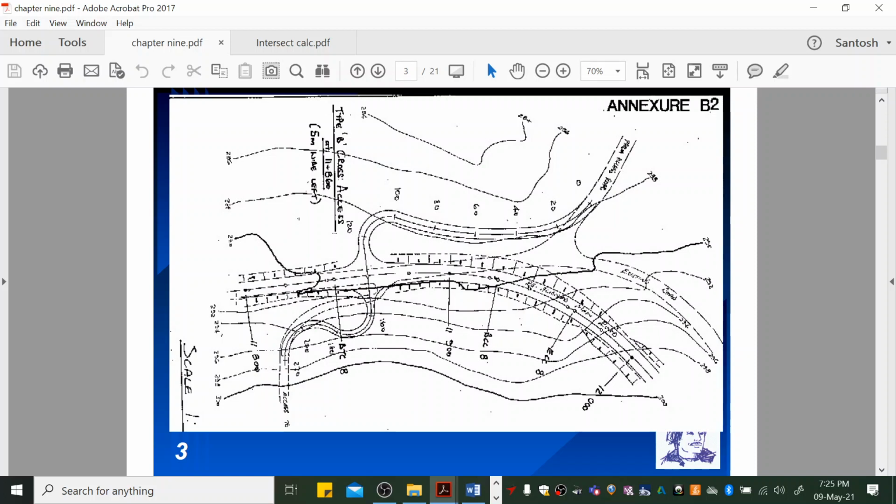So if one looks at it, we've got a main road that runs all the way through here. Then we've got two intersecting roads coming in on each side of the main road. And what basically happens is that the designers extract the ground profile of this road here. And they draw it, and you at Transport 2A will have to design an intersection, how this main road's edge levels tie into the intersecting road and tie into the intersecting road here.